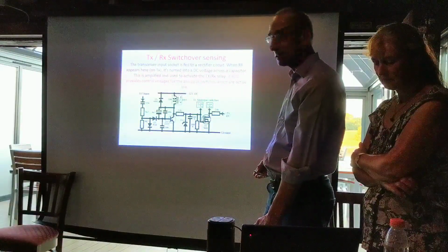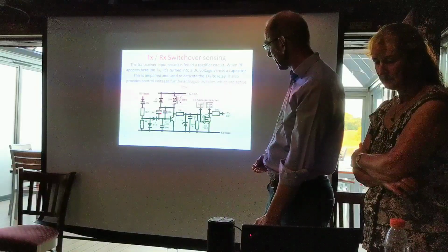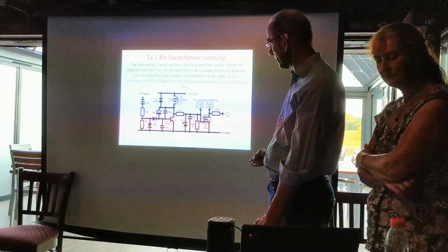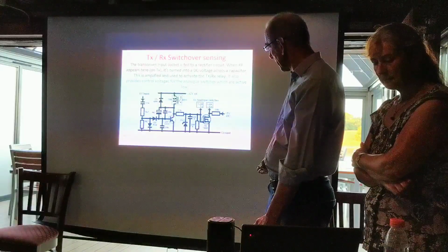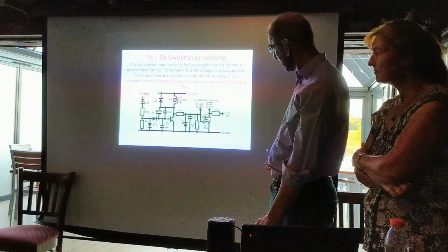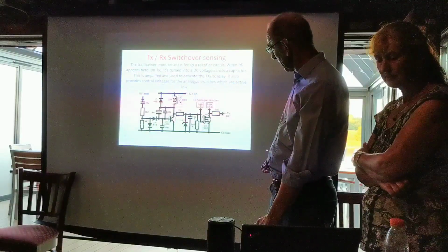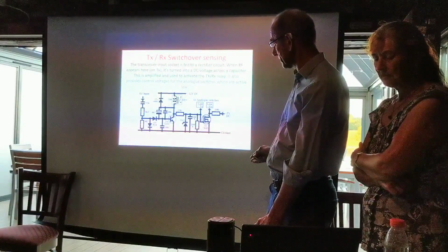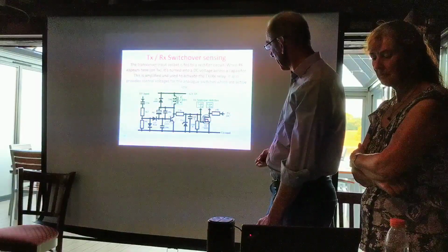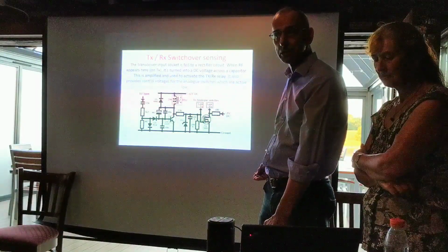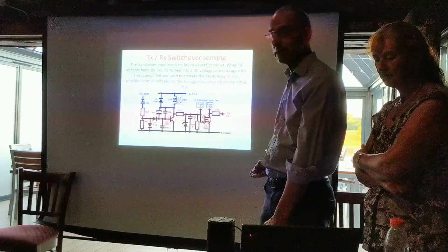The RF is turned into DC, and it charges up this capacitor, operates this transistor and makes the relay go, which switches over the big signals. But of course also we've got those analog switches, so we've got a little bit of extra circuitry here just to limit the values, because those things work at 5 volts, whereas we want 12 volts for the relay. So all that is the switching circuit. That's what's going to make it automatically change over to transmit when you hit the PTT switch.